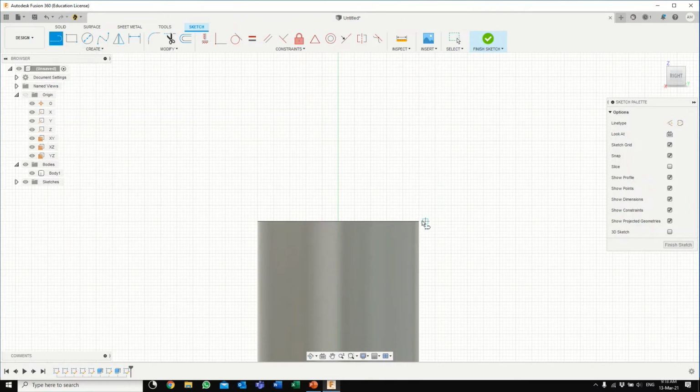and then I'll start drawing using the line. Okay, we know that the thickness here is 5 millimeter. The whole thing is 50, and we have a hollow of 40. So we have 5 on this side and 5 on this side. Okay, and then after you specify the dimension, don't hit enter like AutoCAD, because this will end the command. Instead, just after you insert the dimension, click the mouse, and the command will still be active.